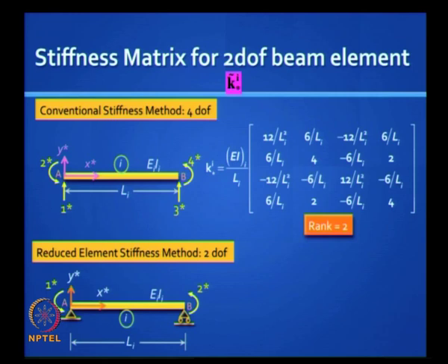Why can't we use a cantilever? You can, it is a good question, you can use a cantilever, please do so, but most of us like simply supported conditions, and we are already familiar with 2 star and 4 star. That 4 EI by L, 2 EI by L is now child's play for all of us. So for sheer convenience we have used simply supported, but you can also use a cantilever. In the book I have discussed this and also used a cantilever as an option, but I do not want to confuse you, go by simply supported, okay, but you can also use it.